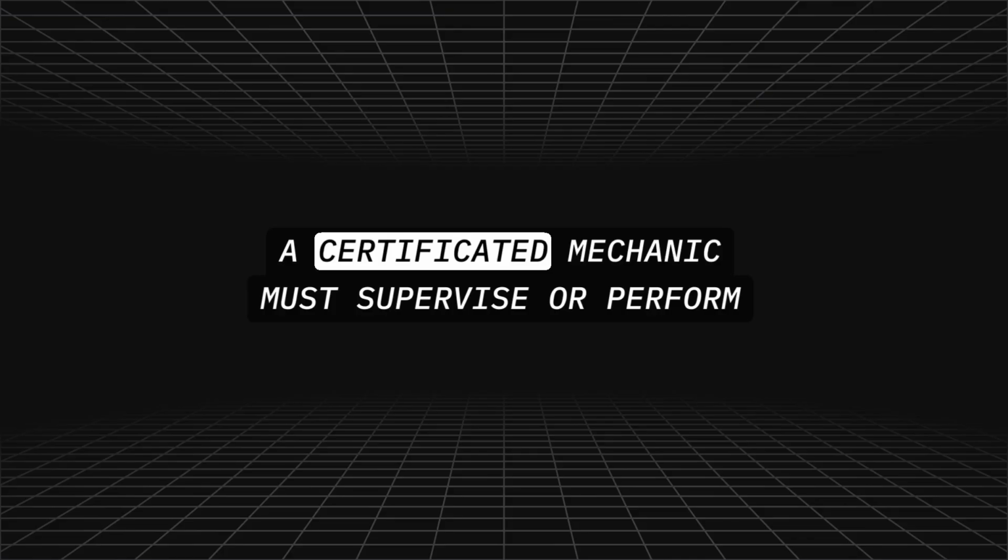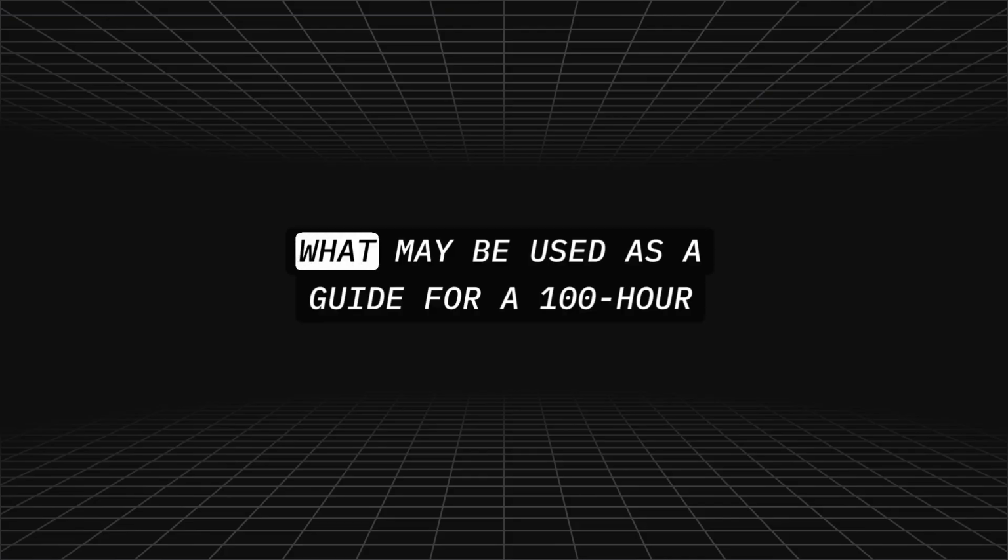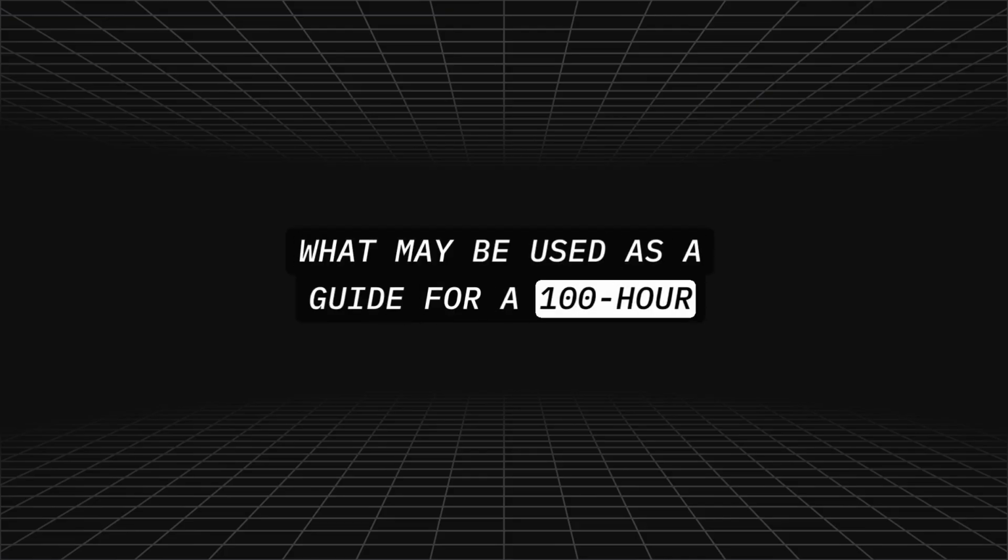A certificated mechanic must supervise or perform maintenance for at least 6 months out of every 24 months. What may be used as a guide for a 100-hour inspection? Title 14 CFR Part 43 Appendix D.